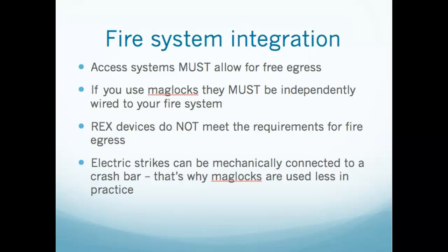REX devices don't meet that requirement. So if you are using mag locks, you have to understand the fire code and you have to make sure you have a fire code qualified fire technician come in to do those terminations so that somebody can get out.